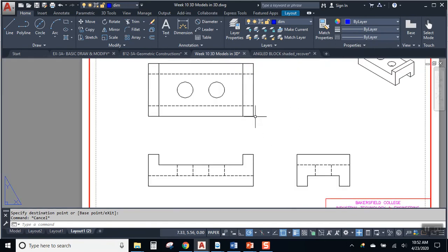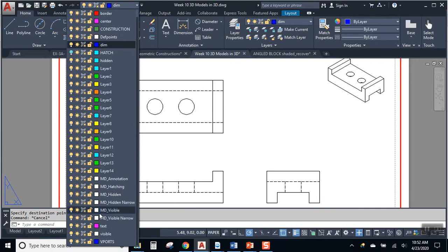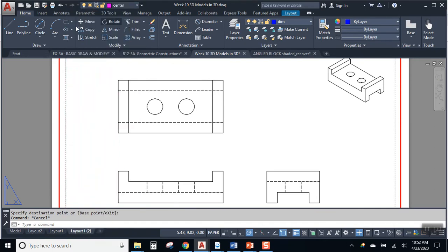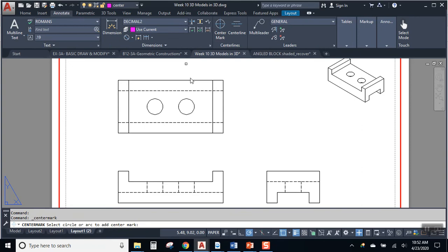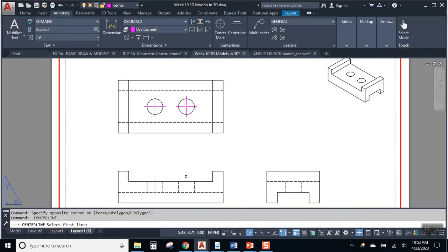And then I'm going to go to town, right? So what do I need? Well, let's just start going through the list. I'm going to need center lines and center marks. I'll do them first. All right, so center mark my two circles, or the holes. Center lines are going to go in between the tunnels. I'll have one there. We'll have another one over here.